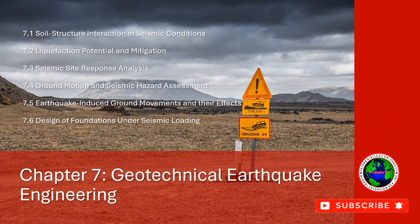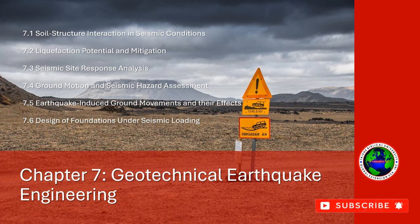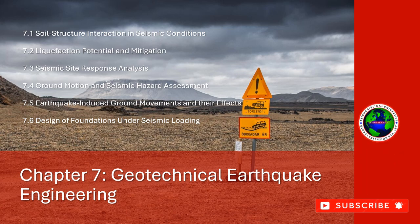4. Flexible infrastructure. For pipelines and utility networks, flexible joints and reinforced materials can reduce the risk of rupture during horizontal ground movements, ensuring that utilities are designed to withstand ground shifts. Placing them in less susceptible areas can also help reduce the risk of damage.